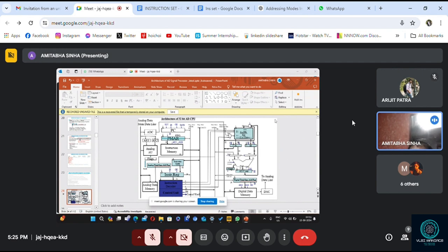Another thing that is very important is that when we design any high-speed processor, it needs a very high clock frequency. Now, if we generate the high clock frequency outside, for example some gigahertz, then due to electromagnetic interference, it will spoil totally.